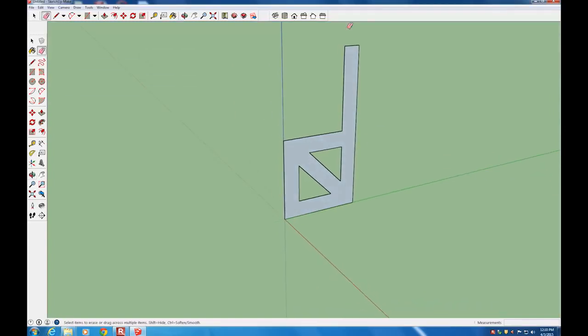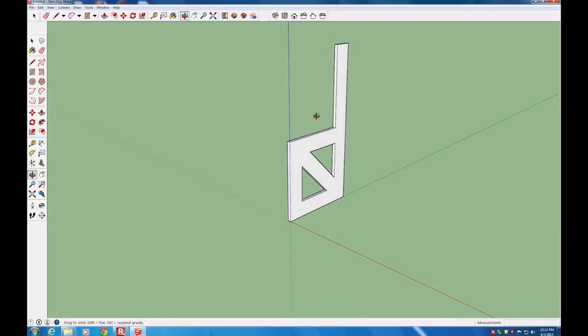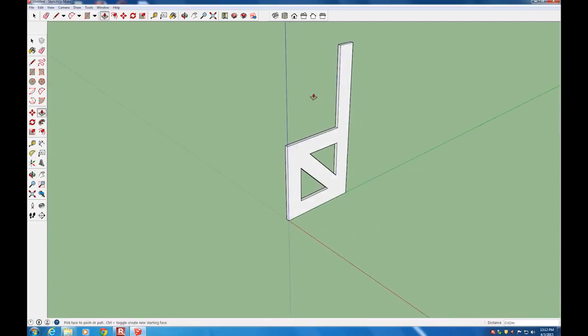And so now I'm going to rotate just a little bit so we can get a better view of the extrude when we do that, and then go over and select from the large tool set the Push-Pull tool, and then hover over the whole face of the chair. It'll highlight blue, and then click and drag the direction we want to go. And we only want to make this 0.02 meters thick. So I type in 0.02 and then enter. And so now our chair has thickness. So we can rotate around, see what's going on. And to rotate, we use the scroll wheel, click, and then drag your mouse. And you'll get navigation of your model.